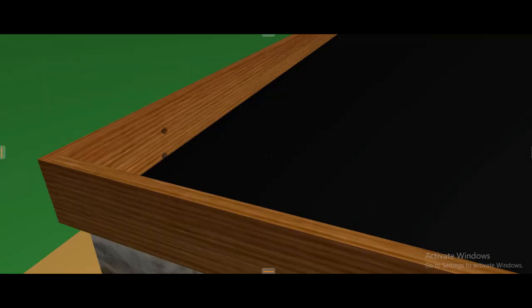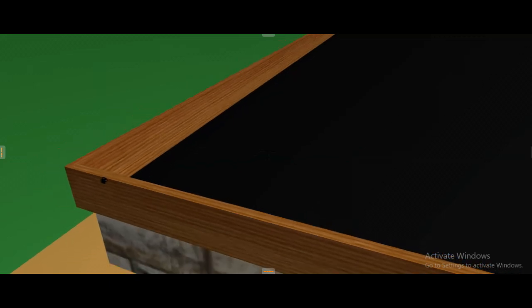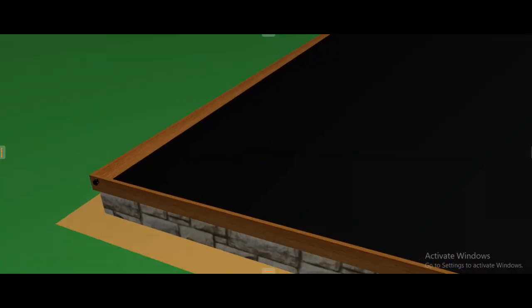So by demonstration, this is the formwork I'm talking about. It is done at the edges of this foundation walling to contain the in situ concrete so that it doesn't spill over, and it is 100 millimeters high. So if I have to enter this one into the squaring column, I simply enter the perimeter. Now let me give you the overview after that close range.